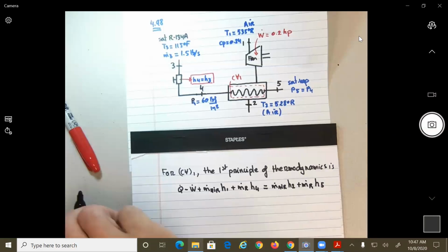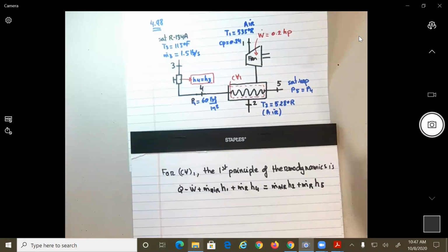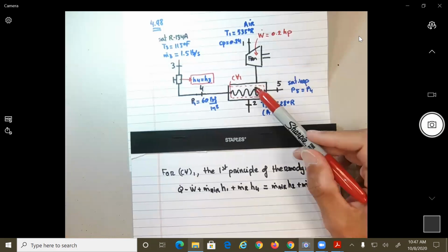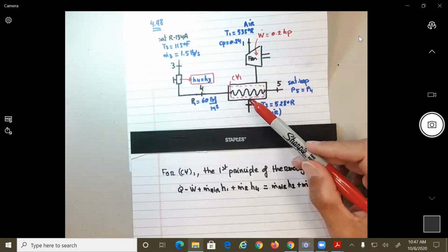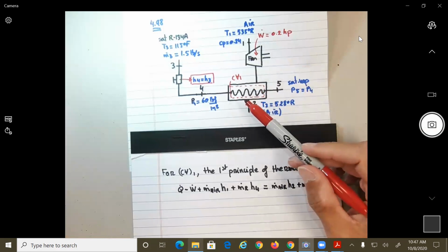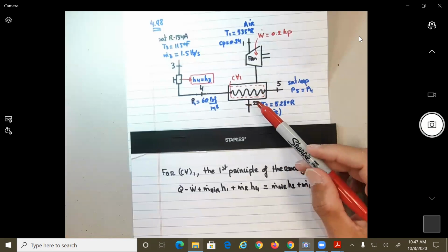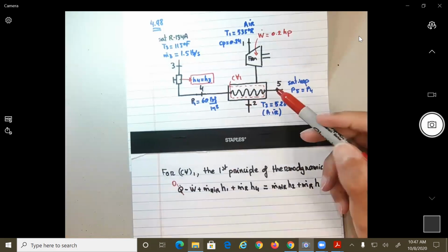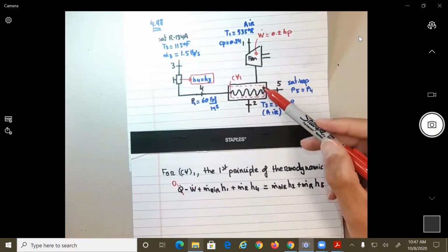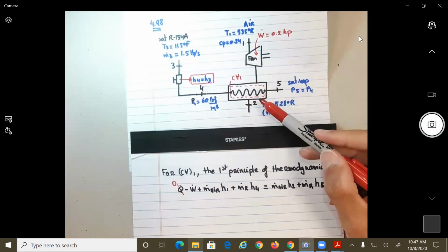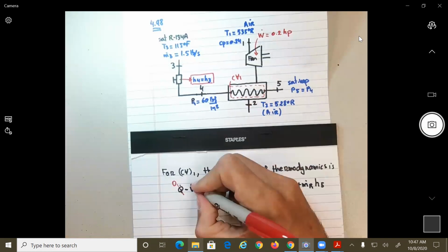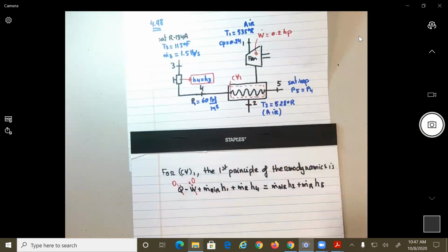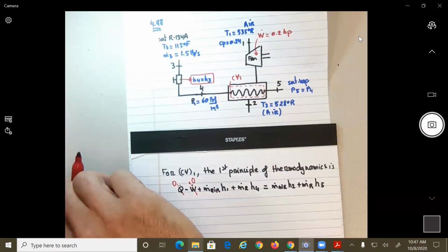So now, this is why the figures are important. In here they give power, but be careful. For this control volume here, is there any heat going in or out? No, you don't see it on the figure, it's not in the equation, so this is 0. Is there any power going inside this control volume? No, so it should be 0. Everything comes from the figure, no? So from here we can rewrite what?